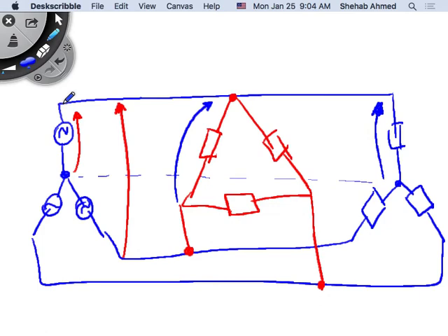And I don't want this to happen, because the single phase equivalent circuit was nice: I was only solving circuits in phase A using the voltage source in phase A, and solving for currents in the loads on phase B using the voltage source on phase B. But now I have a relationship between phase AB voltage and current in phase A, for example. So I don't like that.